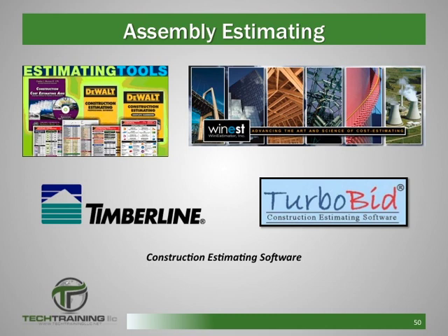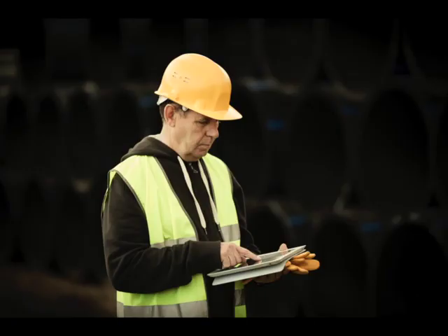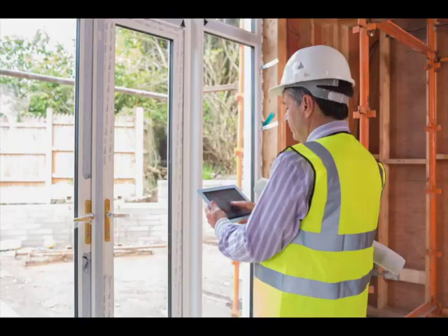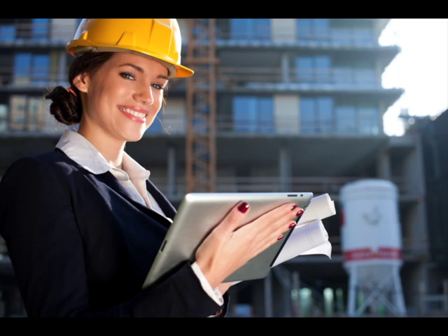Many high-end estimating computer programs such as WinEst or Timberline allow the user to prepare a detailed estimate by taking off the assemblies. As an example, for the switch assembly, the estimator would take off the number of switch assemblies needed for the project, and then the software would add a single gang box, cover plate, wire nuts, and so on to the detailed estimate for each switch assembly. This simplifies the estimating process and increases the productivity of the estimator.